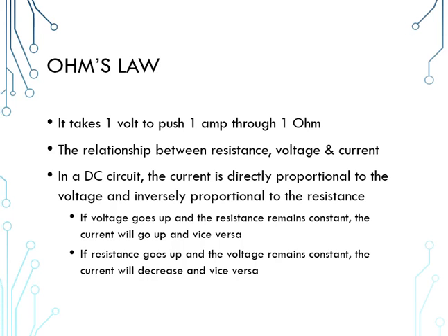So we'll start by making a voltage reading. That is the easiest measurement to make because we use a voltmeter in parallel to a circuit, so we don't have to do anything special to the circuit like turn it off or disconnect something. We don't have to use the lockout tagouts. We simply set it on the right setting on our multimeter, either DC voltage or AC voltage.